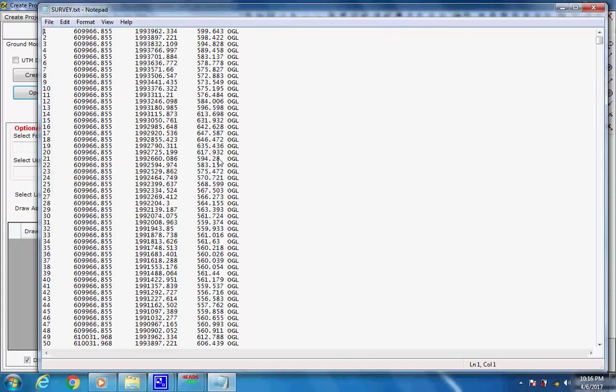The above data may be either in Surveyor's Transverse Mercator, TM, coordinates or in Universal Transverse Mercator, UTM, coordinates. If the data is in TM coordinates, then these are to be converted into UTM coordinates by using GPS UTM coordinates on points with TM coordinates.